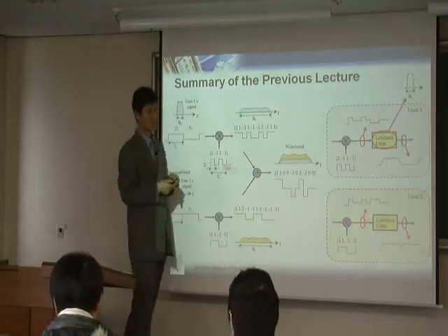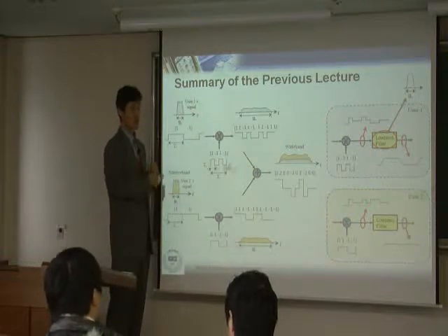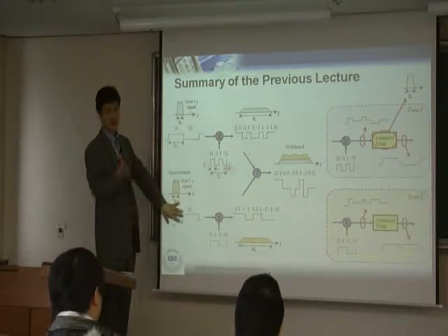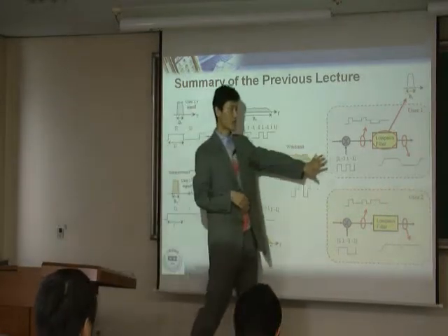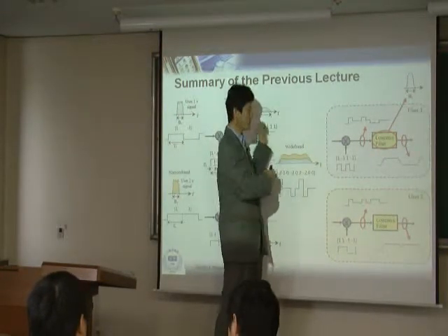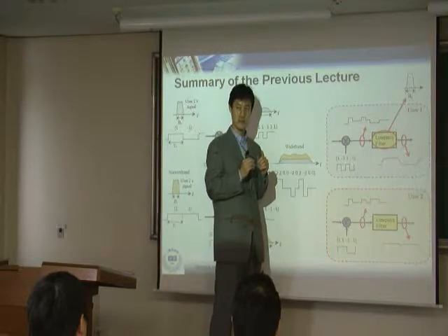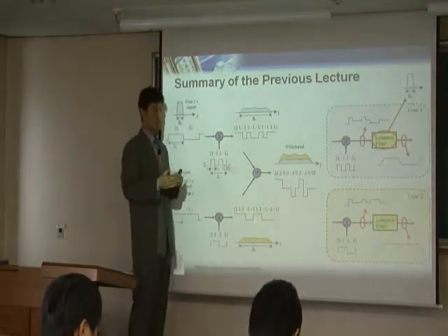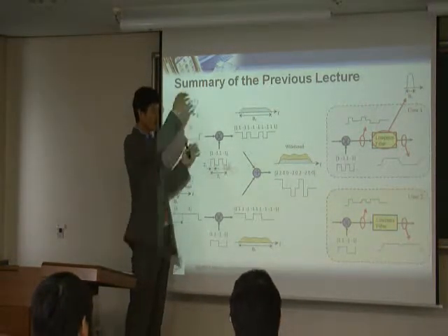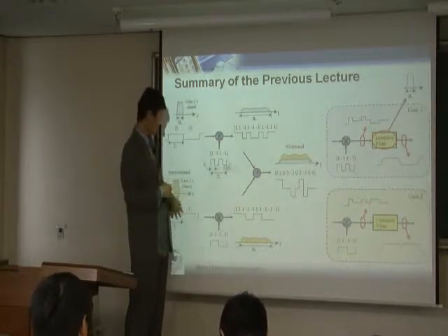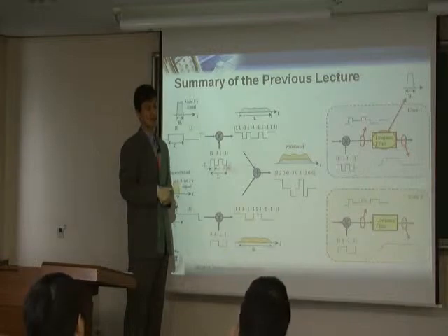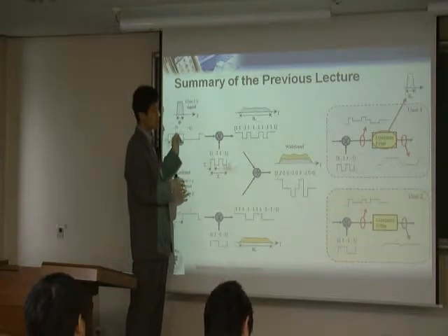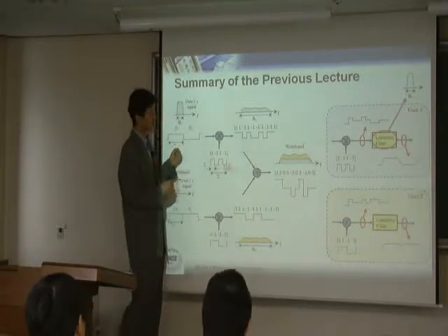That's the most important thing for CDMA to operate correctly, okay? So it doesn't matter whether this guy is close by or very far away. For the base station, it wants to receive this power at the same level, okay? If that's a different level, we now experience some near-far problem. Maybe a little bit off is okay, but if this power is so big and this power is so low, then user 2 is completely shadowed, right? So that's the problem. That's why power control is such a big concern in CDMA.